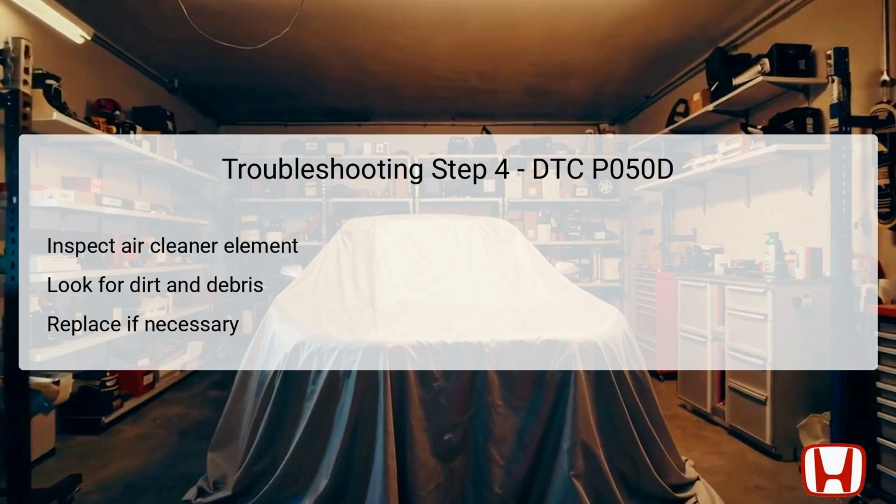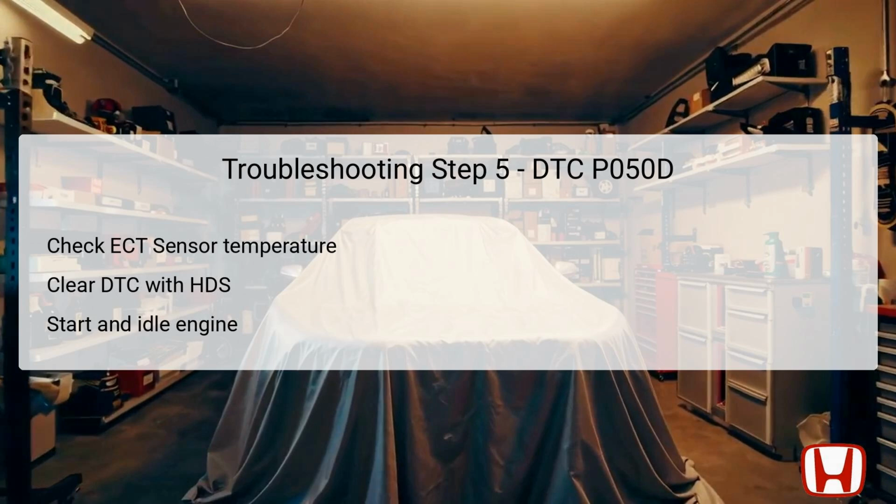vehicle's engine. The fifth troubleshooting step focuses on problem verification, particularly concerning the engine coolant temperature, ECT sensor. Begin by allowing the engine to cool until the ECT sensor 1 registers a temperature of 122 degrees Fahrenheit, 50 degrees Celsius or less. Utilizing the HDS, clear any existing DTCs before starting the engine.